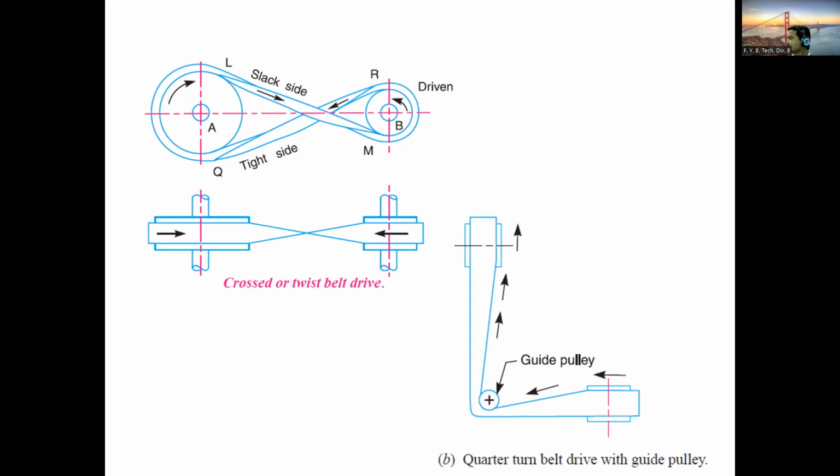What may be the drawback? In open belt there are advantages, but here in cross belt we call it a disadvantage. Think about the two belts bending and rubbing against each other whenever there is a rotation transmission. So the wear and tear of the belt is more. Is this economically affordable or unaffordable?